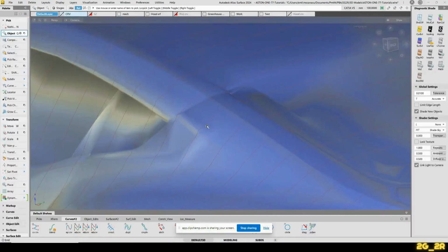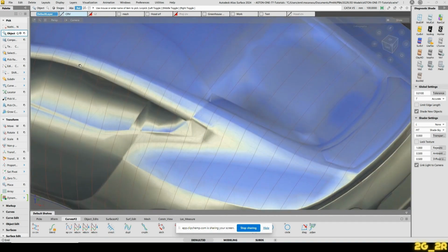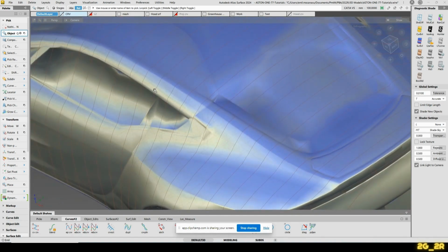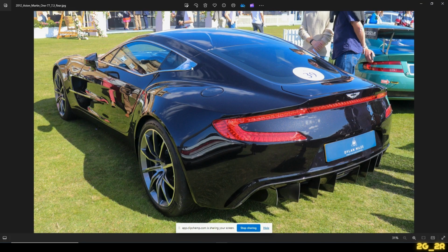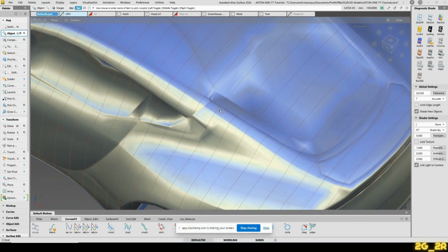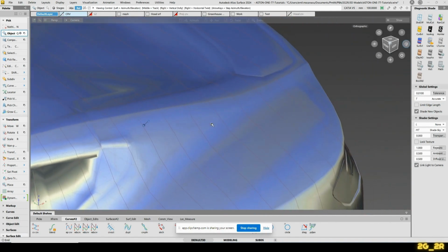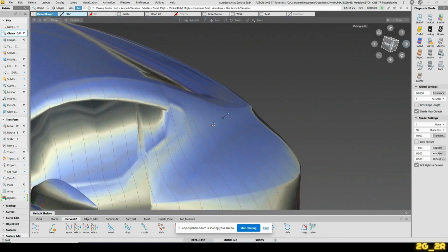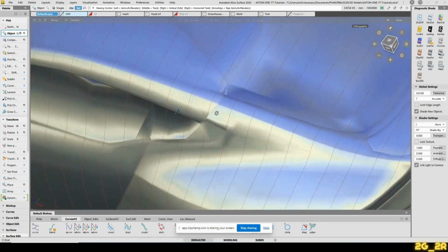So let's go into the model and see what we've got there. When you see meshes like this that are well defined, in the meaning that a sock is a well defined object, going to images will help you a lot to get a better reference of what you need to be doing. So here I'm going to use the edges that we've got here. I'm going to be referencing these sections, so I'll try to make the surfaces resemble as much as we can to this here. And that will be the one thing that's going to drive the surfacing of this area.